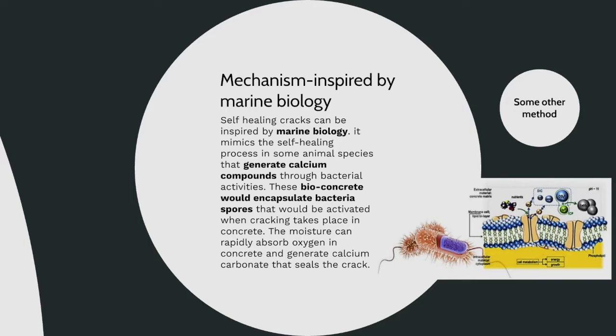And that calcium carbonate will seal the crack. Okay. So a crack happens, and then the moisture will change because there will be at least water or air coming in, right? And then because of the reaction inside, the bacteria absorb the oxygen and generate the calcium compounds. It has been developed quite well established, I think, the bacteria.